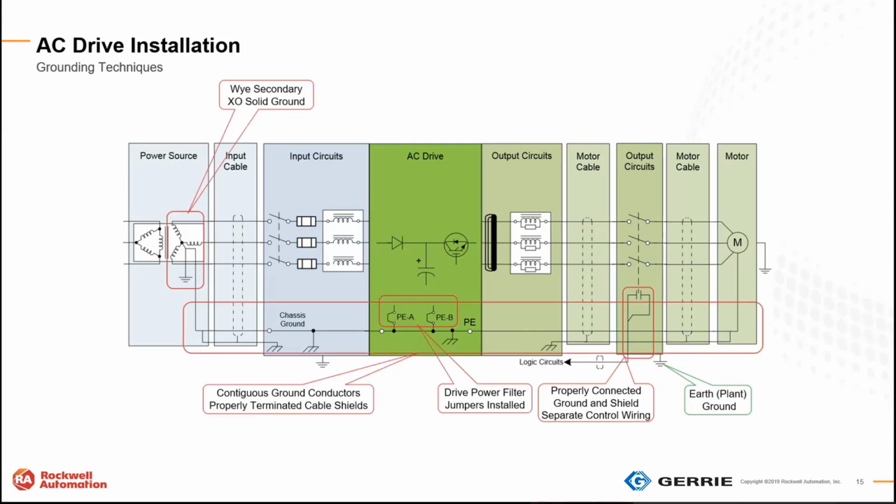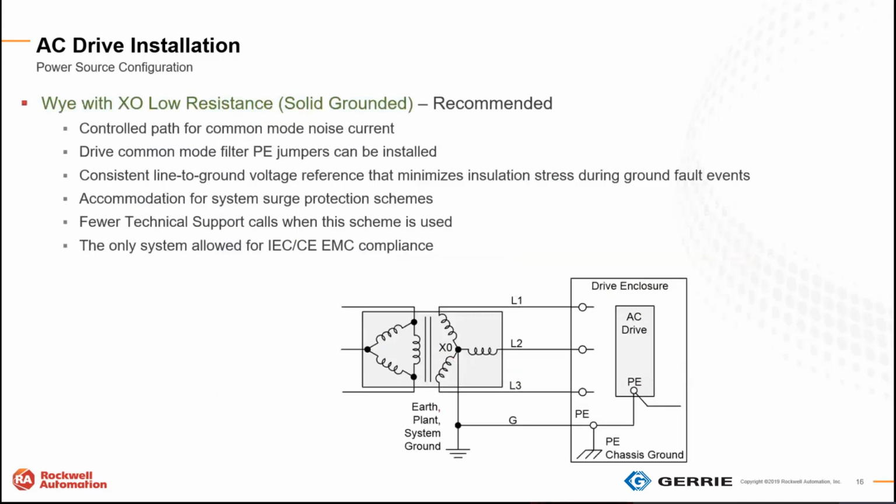What else we got here? In general, all the good grounding practices result in a solidly grounded system that we typically don't see a whole lot of issues with. Oftentimes, if we are having problems or some random nuisance things happening, the first thing we look at is how is it grounded. It's not just at the drive itself; we want to see the whole system, from the motor right to the power sources, and how things have been installed.